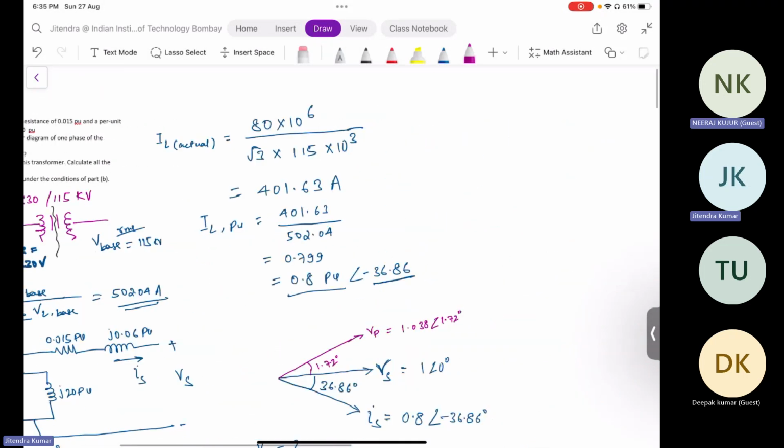So when we calculated by the long method, you told us it might be beneficial, time-saving, to use the per unit values to calculate. For calculating that, you told that S is 0.8 per unit and V is 1 per unit. So your I will be 0.8 per unit. Yes, sir. So here we did not consider the root three factor. That's what you want to say.